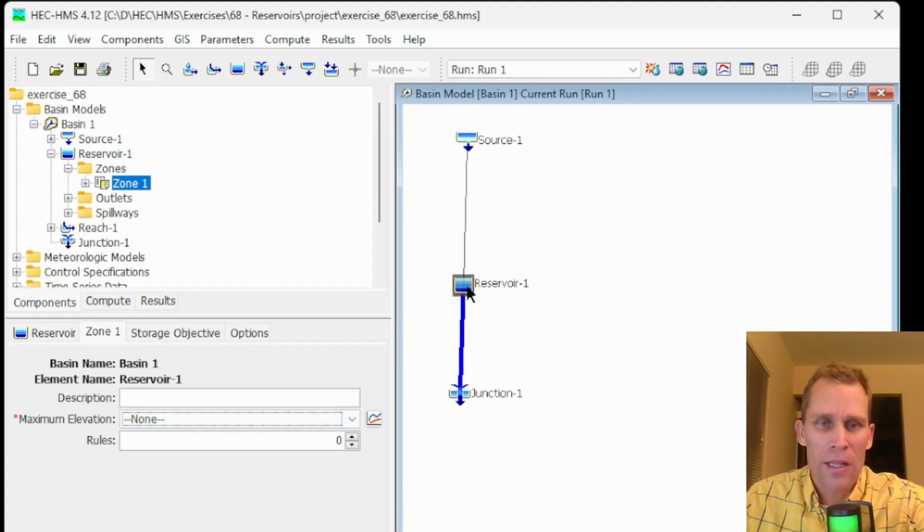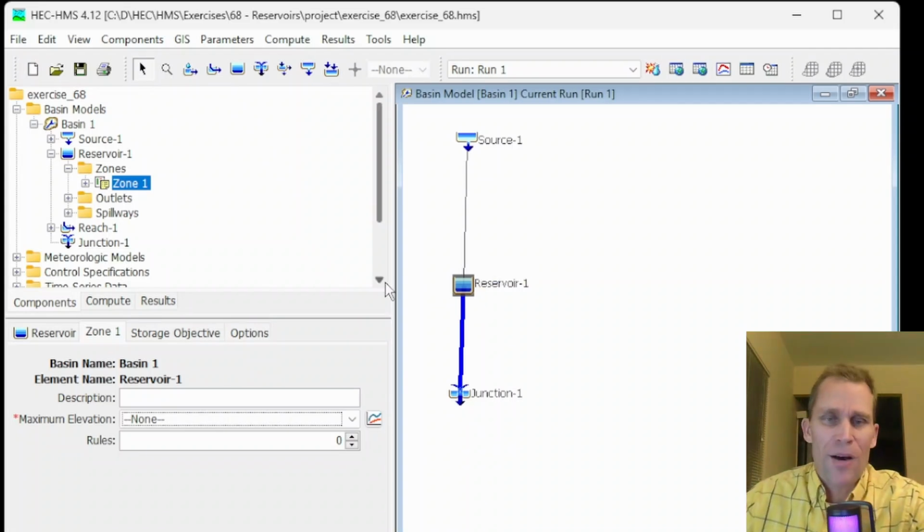Keep in mind that the top elevation of the reservoir is 1500. So if I set an elevation above 1500 and make it my only zone, then that's one way to keep all the reservoir operations for the entire simulation in that one zone. That's the safe way to do it. So I could just be absurd and call it 1600, because the water surface will never get above 100 feet above the dam face.